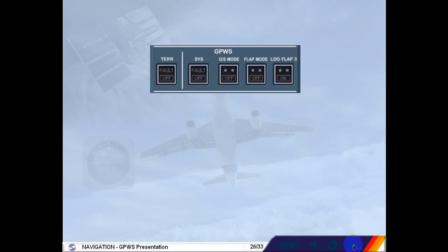The Enhanced Ground Proximity Warning System uses a terrain database coupled with an FMGS position to calculate two terrain envelopes ahead of the aircraft. When a conflict is detected between these terrain envelopes and the terrain memorized in the database, an alert is triggered. One terrain envelope corresponds to a caution level, while the second one corresponds to a warning level.